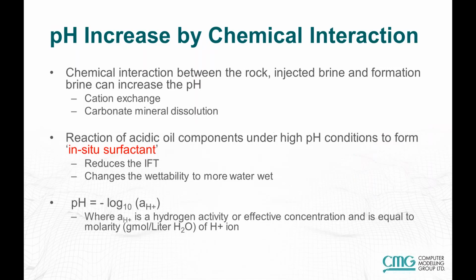There's also a pH increase by the chemical interaction between rock, the injected brine, and formation brine, and that may be caused by either cation exchange or carbonate mineral dissolution. Once the high pH occurs, it can react with the acid in the oil to give an in situ surfactant. If that occurs, then the surfactant will reduce the interfacial tension and change the wettability to more water wet.